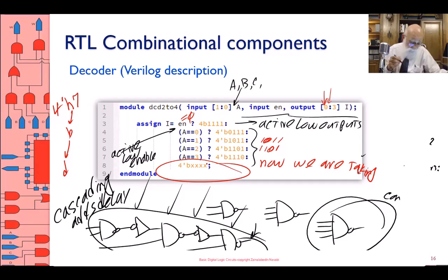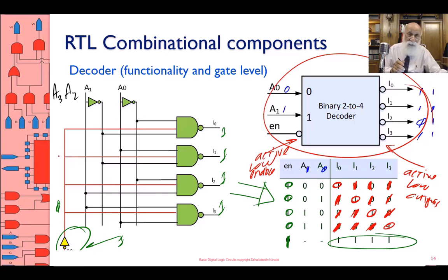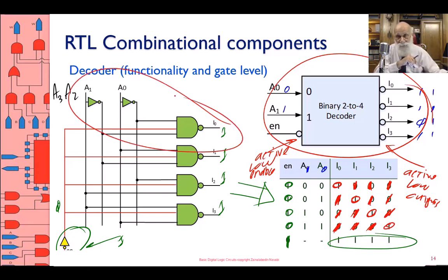All right, so this is the Verilog description of it, using assign statement, using condition operator. If you wanted to, you could go back here and describe each output using the NAND functionality of it. You could write this NAND circuit completely as is here, using NAND primitive.